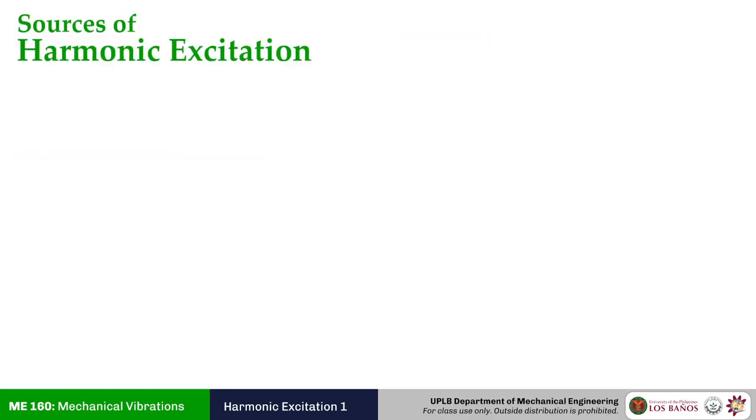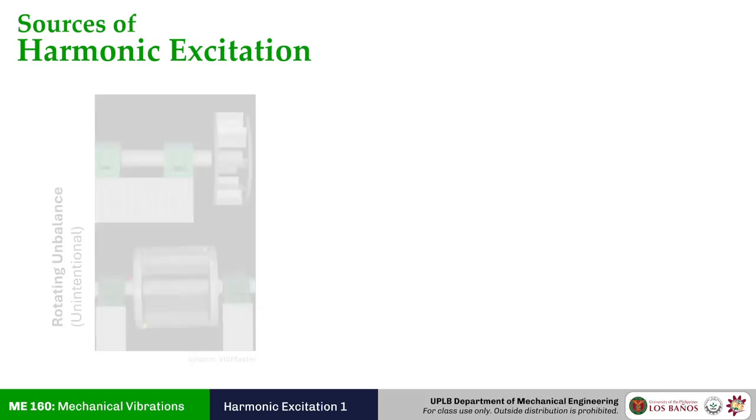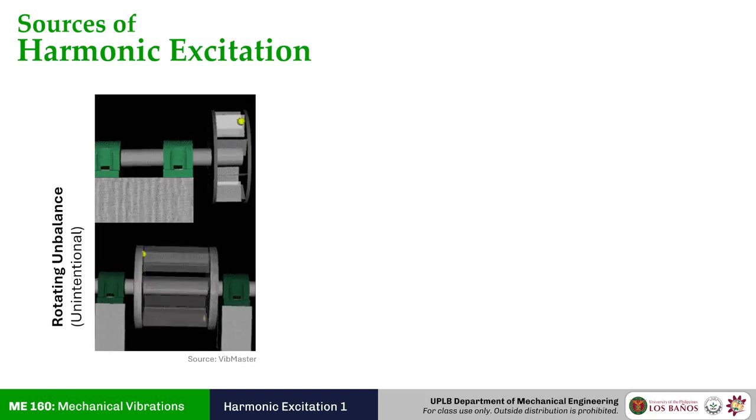All right. So where can I, as an engineer, observe harmonic excitation? Around our industry, there are plenty of sources of harmonic excitation. One of them could be a badly balanced fan or badly balanced impeller. This results in a lot of shaking, and it will be high frequency shaking, knowing the speeds at which fans and impellers run. Depending on the integrity of your component, it could fall apart catastrophically if nothing is done.